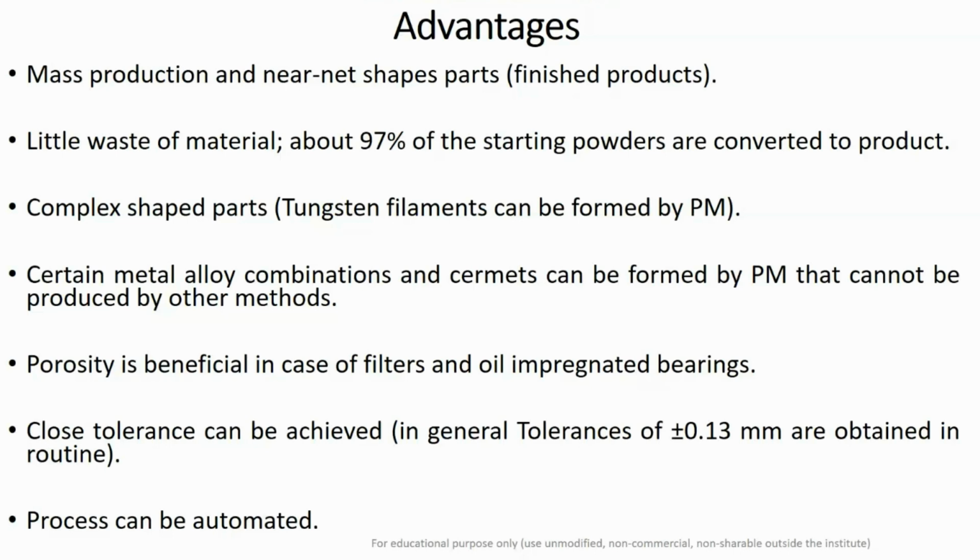You just take raw material from the supplier, and then you put all the raw material on a conveyor belt. This conveyor belt first feeds the powder into the mixer, and from there the mixed powder pours into the powder feeder, which sends the powder through flow tubes into the die cavity.